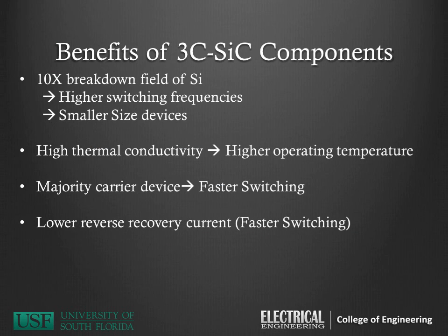Some of the benefits based on the previous tables include 10 times the breakdown field of Si, which enables higher switching frequencies, which will in turn equate to smaller sized devices. There's a higher thermal conductivity, which equates to higher operating temperatures. These are majority carrier devices, again equating to faster switching, and there's a lower reverse recovery current, as we'll see in the following slides.